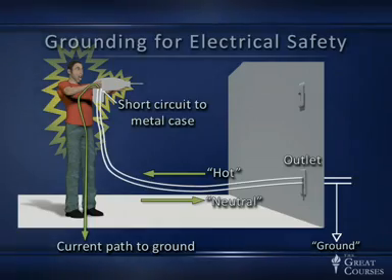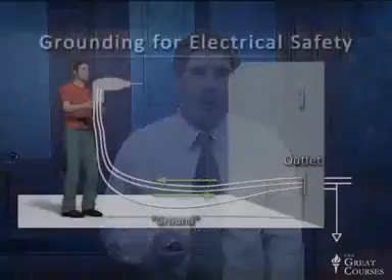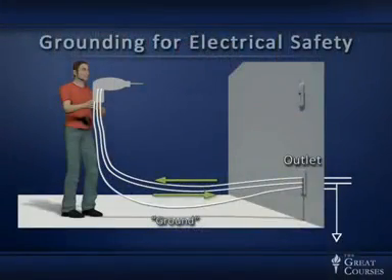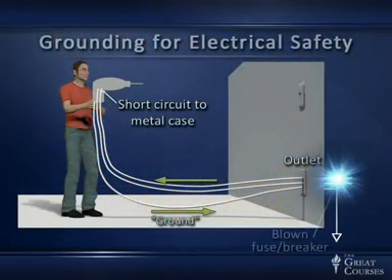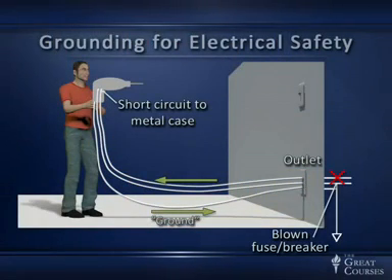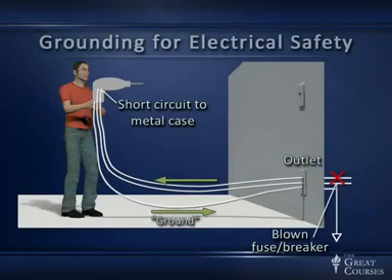So to avoid that problem, many devices that we're likely to use in situations where we'd be in contact with grounded things like water pipes, for example, so in the kitchen with power tools and so on, we add a third wire, a ground wire, and then if there's a short circuit to that case, the current flows down the ground wire and it breaks the circuit breaker or the fuse that protects that circuit from short circuits, which could otherwise cause fires because too much current would flow.